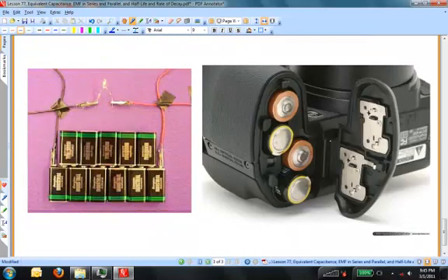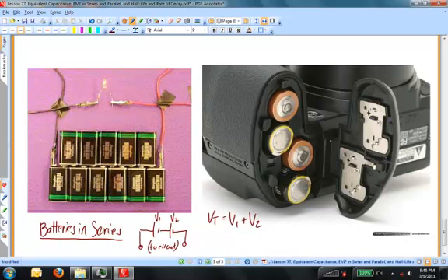Whenever you load a battery-powered device, such as a digital camera, as in this diagram on the right, or a flashlight, or battery-powered toy with more than one cell, you're connecting those batteries in series. These photos show batteries connected in series. When you do that, the total potential difference of the network is boosted. If you put four 1 1/2 volt cells together to power your radio, you've created a power source with a 6-volt potential difference. For batteries in series, the voltages add, whereas the current through each of the batteries is identical, because there's only one path for the current to follow.